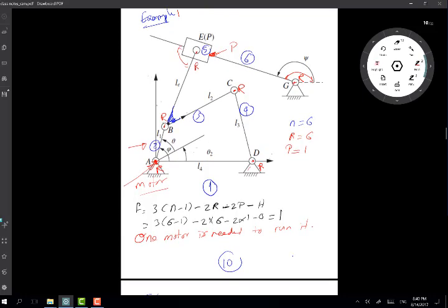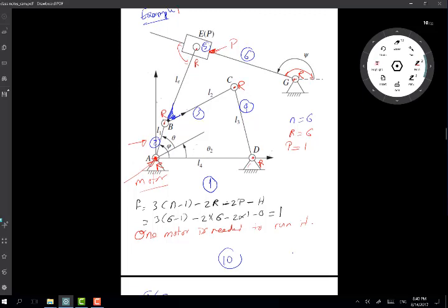The torque from the motor will be low at the link 2 end where the motor is fitted, and then the torque will be magnified at other links, just like levers do. So linkages do torque magnification as well, as we'll discover soon in this lecture series.